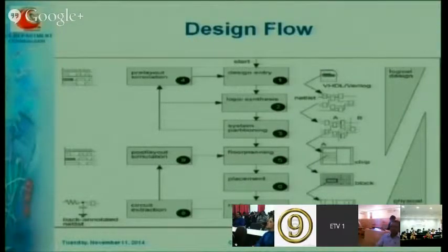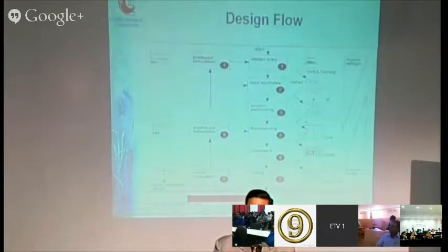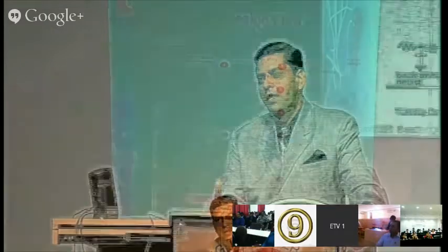Whenever we go for design on any platform, let us say we are designing our circuit on FPGAs, or on ASICs, where ASIC stands for application specific integrated circuits, the first thing is we have to select the floor out of the available different floors. Once that floor is selected, then we have to select a particular portion of that floor where your circuit is going to be placed. So before placement, floor planning is very important, and once the floor is decided, then we can place our circuit at a specific portion on that particular floor.